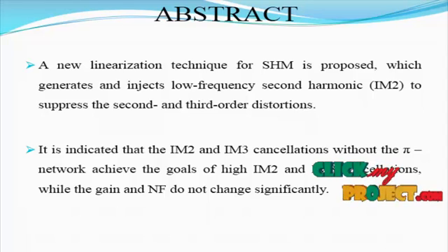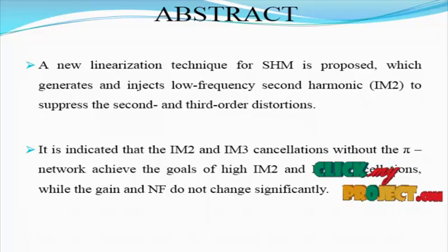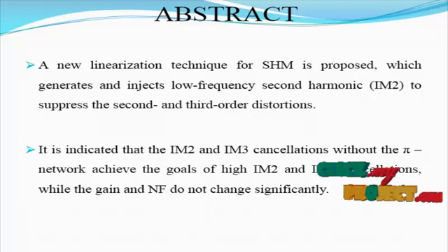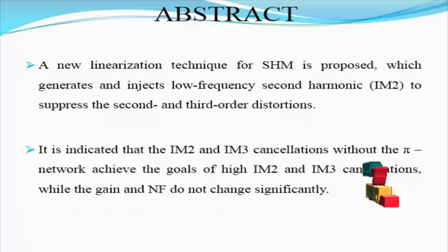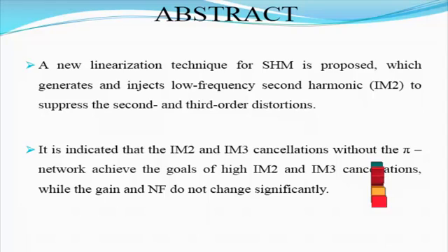Another issue is the limited dynamic range of the mixer, which normally consists of many more components than LNAs, and has to process much stronger signals due to the amplification provided by the latter. Therefore, mixers are the main source of intermodulation distortion in the receiver chain, especially second and third order intermodulation